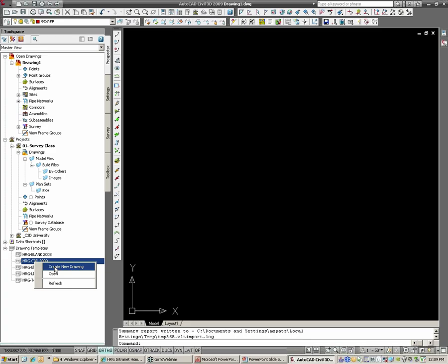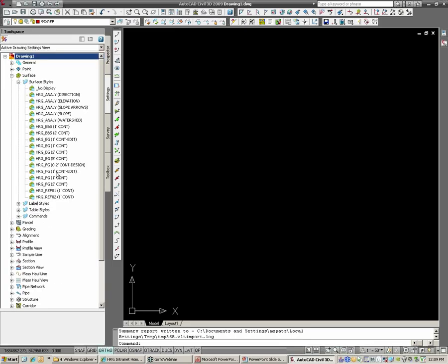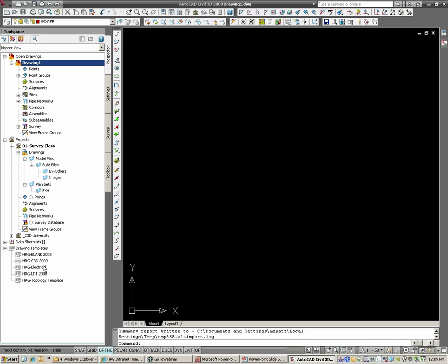If you first launch Civil 3D, you notice it does open with a drawing here, this Drawing 01. You can go in there and you can actually see this is started with the template because it has styles in it. Now, the program's very tricky because Drawing 1, when it first opens, is started from the template, but if it opens a Drawing 2, 3, or 4, when checking files in and out, those are not started with the template. I live by the law: don't trust it. Just always come down here, carefully click on this slowly, and hit Create New Drawing.